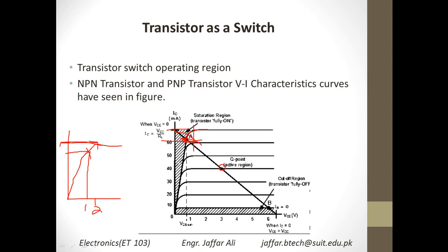So this is basically a characteristic diagram that is showing you the relationship between the voltage and the current, output current versus the output voltage. You see that as much as you increase the voltage, your current increases, but at some time when the switch is completely on, it doesn't matter how much you increase the voltage, because if you increase the voltage further, the current will be constant because it has gone into a saturation region.